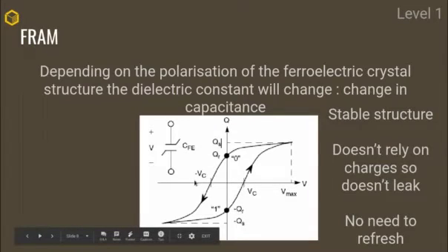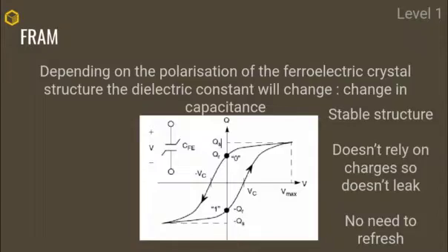This is quite interesting because unlike the DRAM cells where we're storing charge, here we're basically storing the information as a polarization of a stable crystal. And so this does not leak charge because it is not charged by definition, and also is rather stable. So there's also no need to refresh it because it doesn't lose charge simply over time while idle.